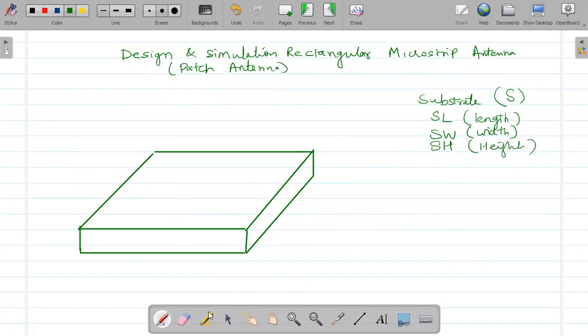It is a fundamental part that in a microstrip antenna, we have a substrate which is of insulating material. It is an insulator, and insulating materials have a dielectric permittivity. So a relative dielectric permittivity epsilon R is there with this insulating substrate. Now, at the bottom of this one, we are going to create a plane, and let me draw it with a red color.